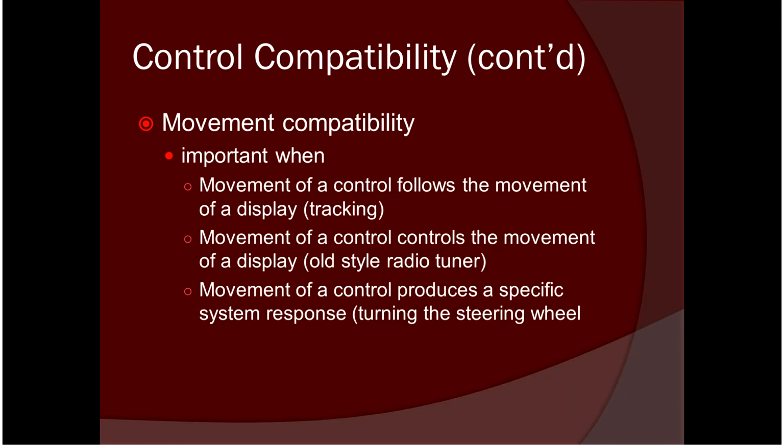There's also movement compatibility. That's when you see a display that's moving according to how you're matching up with the control. So, for example, if I turn the control to the right and it's a round dial, then the needle should move to the right, right? If I could, but unfortunately, there are other issues there, because a lot of times I've been turning a round control to move a display that's on a linear scale, right?